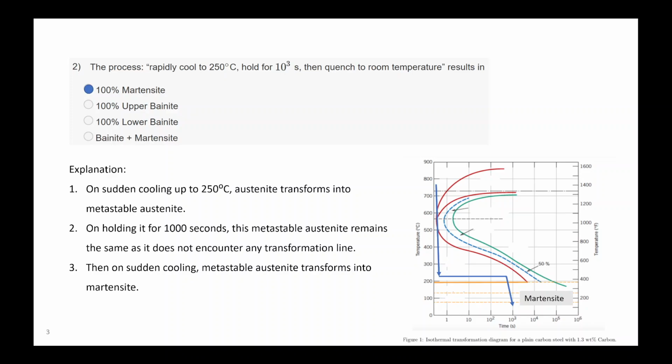For example, in diamond there is no free electron, so it is dominated by phonons. In the case of metals, you already have free electrons. So at high temperature, the movement is restricted. That's why it will decrease at higher temperature, similar to your electrical conductivity.